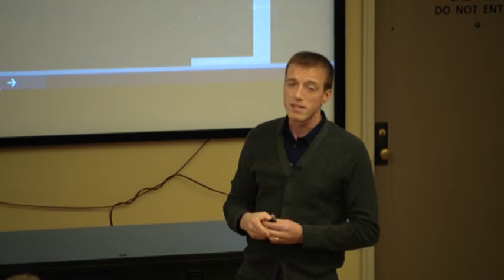So then the last bit is effects analysis. Effects analysis is, okay, something went wrong, what happened, right? What's the severity of the outcome? Is it just that my project is late for a week and my project partner is upset with me, or is it that a kid gets electrocuted and that's a big problem, right? So you're going to look at those and set them in the context of your specific analysis. So a 10 out of 10 severity on one FMEA doesn't match a 10 out of 10 on another. It's not an absolute scale. You have to scale it to the problem that you have at hand, okay? So that's something that you'll want to communicate in your FMEA.